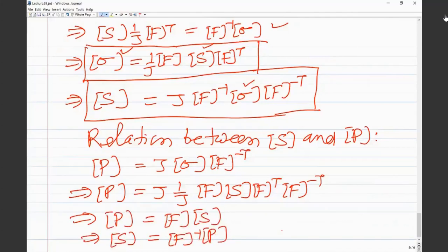So these are the relationships between Cauchy stress, first Piola-Kirchhoff stress tensor and second Piola-Kirchhoff stress tensor, and the major role is played by the deformation gradient F. Now if the displacement gradients are small, that is, the elements of F such as del u1 by del x1 and so on, then F will be close to the identity matrix and J would be almost unity.